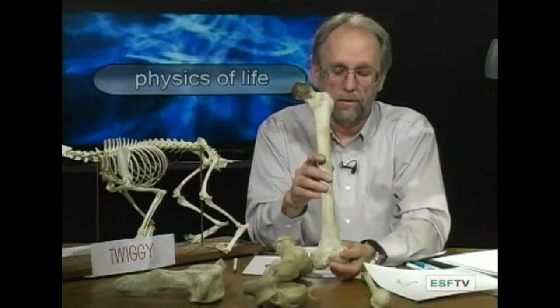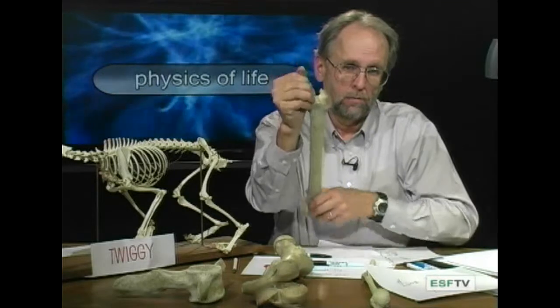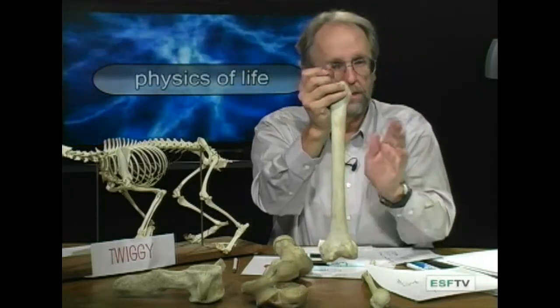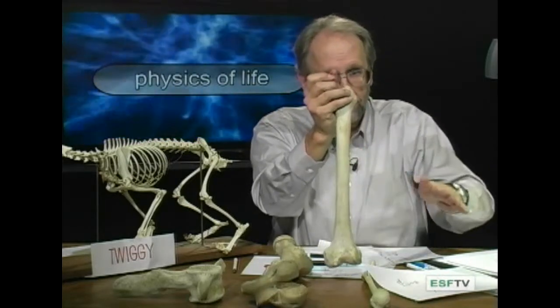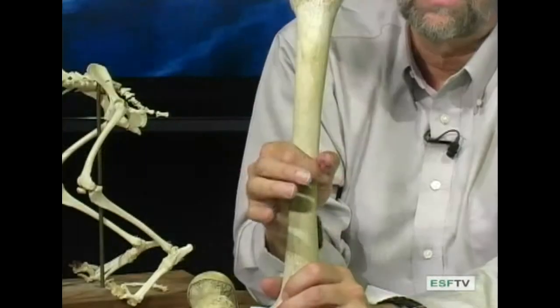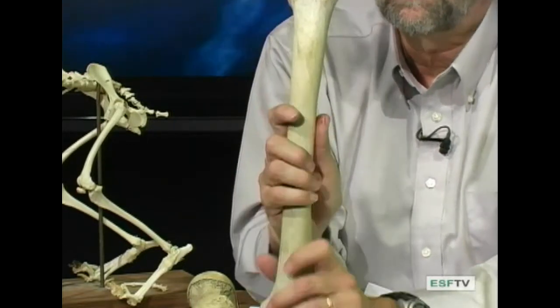And so, for example, if we look at the way the femur sits in our own body, this is the left femur here, then when the person is walking forward, the main direction of movement and the main direction of bending is going to be in this plane right here. But if you're coming along and you're running and you suddenly change direction, you're going to be experiencing a stress in the bone that's going to be going this way. The point is that the stresses and strains that are experienced by a femur can come from any direction. And the best design for a bone in that instance is to have a circular cross-section, that is something that can resist flexural deformation equally with strains coming from all sides.